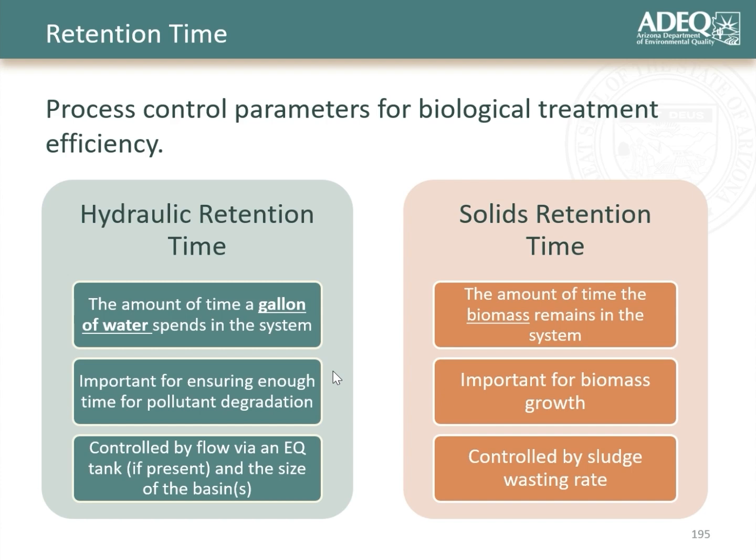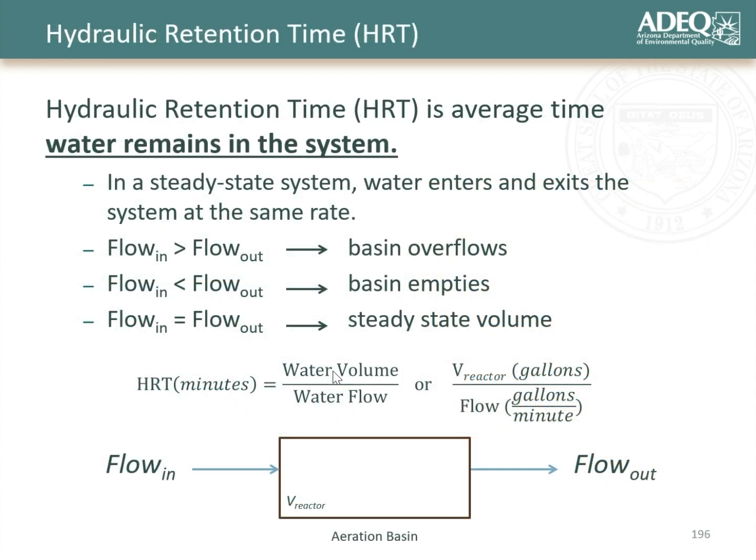The solids retention time is the amount of time that the biomass stays in the system. And because we have the return activated sludge system, that changes the residence time from what the hydraulic retention time would be. And that is ultimately controlled by your sludge wasting rate, which we're going to be talking about in the next few slides. So with the hydraulic retention time, this is the average time the water stays in the system, as we mentioned before.